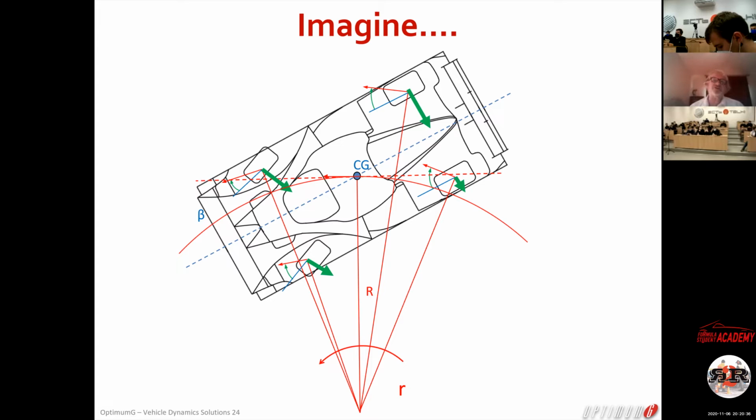If I change the 4 lateral grips, do you agree that I change the lateral acceleration, for the best or the worst? 0.1% or 5%, I don't know, but I change something, and I change the yaw moment. So I change the grip and I change the balance. The grip is the sum of the 4 grip. The balance is the yaw moment.